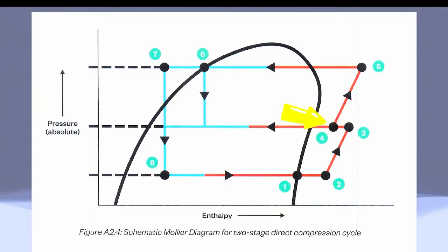Remember, this is what we talked about. It reduces the load on our compressor on the second stage. That's it. From point 4 to point 5 is the second stage of compression. In this phase, the pressure increases once again, rising to the level we need, to the final target level, and then from point 5 to point 6, condensation takes place as it is cooled with seawater during the transition from point 6 to point 7. Here we have a liquid cooling system partially running through the intercooler.